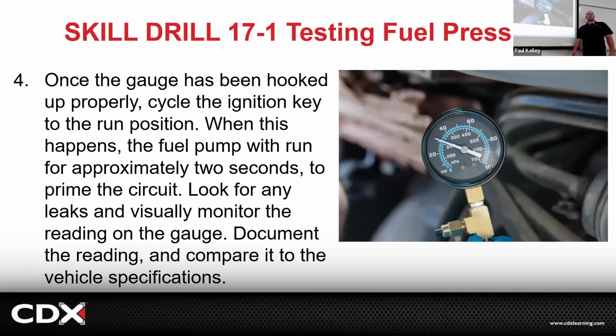But what if you have a car that has a loss of power under heavy acceleration? This would make sense. I see it now on the acceleration. True, and it would lose a ton of power too. So you'd be wide open, and it's pulling in air, but it can't match it with the fuel. So it's not going to make enough power. It's going to be loss of power. This would make perfect sense. I've even seen where it makes 50 PSI at idle, but then when you slap the gas pedal, the injectors are like, yeah, freedom, and then the fuel pump's like, wait a minute, I can't pump that much.